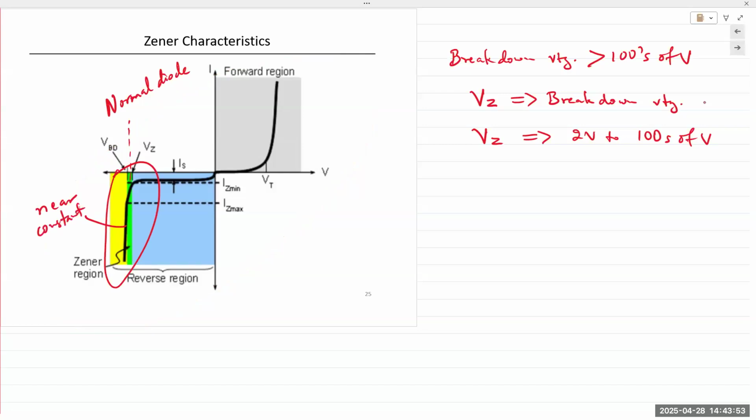Even the slight slope that you see here at the curve at the beginning of breakdown, even that is exaggerated. We perform experiments using Zener diodes in other lab classes, and we use 5.7 or 6 volt Zener diodes, and there's barely any difference between the breakdown and once it crosses the breakdown. So barely millivolts difference, but the current increases by large amounts. And so again, this is quite large.